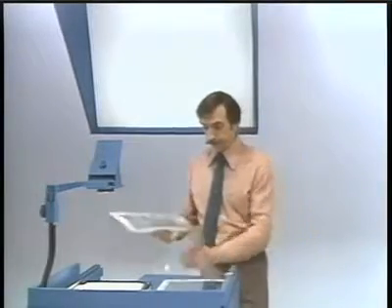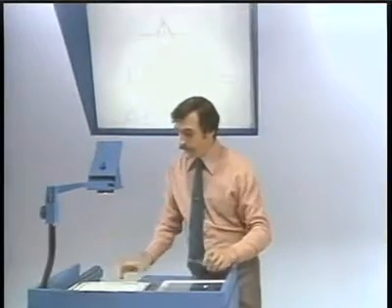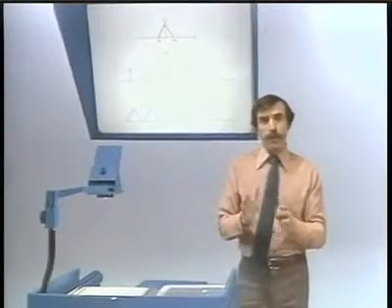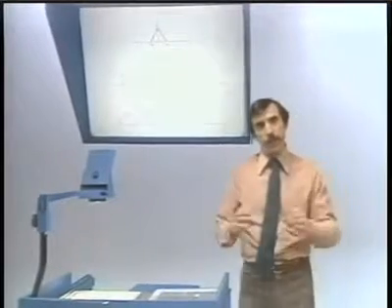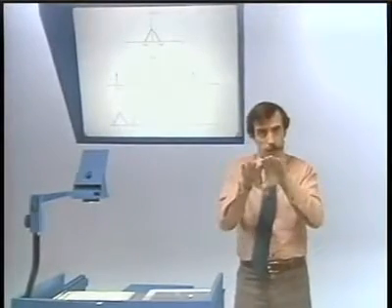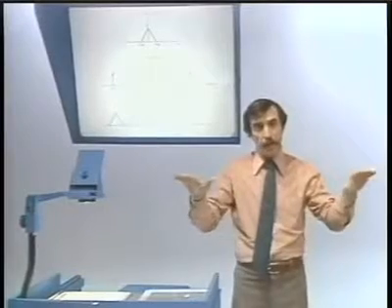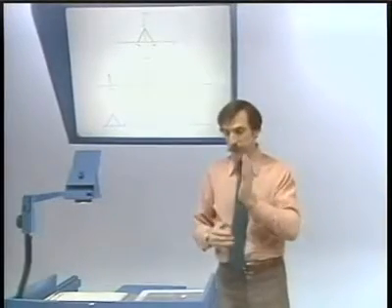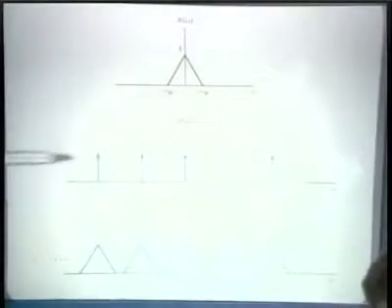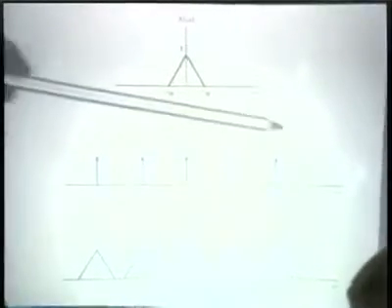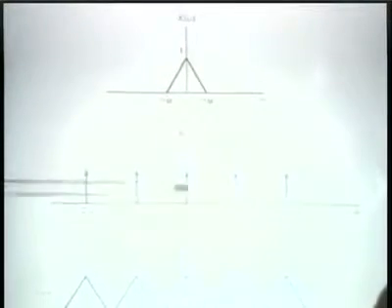And so now what we're talking about is a spectrum that consists of the result of the spectrum we talked about before with a sine x over x envelope, except that now as delta goes to 0, that becomes flat. In other words, the modulating signal is an impulse train. And so as we look at the spectrum of the modulating signal, that is then an impulse train in the frequency domain.